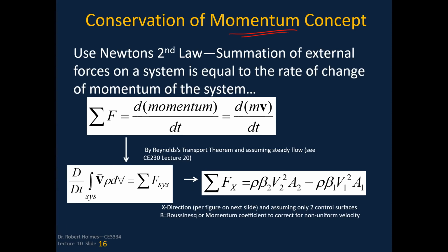And out of that, we're going to get an equation that describes the bed shear stress, which we're not going to use a lot in this class. We're going to use it a little bit. But more importantly, it's on our way to getting at what we call the flow resistance equation. The biggest equation you're going to use in open channel hydraulics consistently is something called the Manning equation, especially in the United States, or the Chezy equation, which is what they use in Europe. Sometimes we use it in the US, but predominantly the Manning equation.